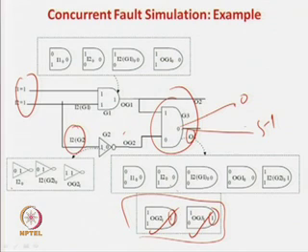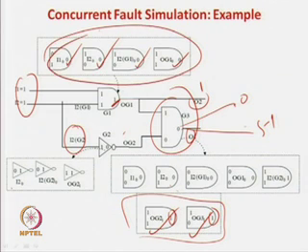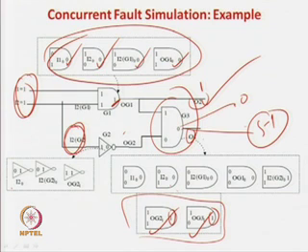But similarly, you can see that at O2 also some faults can be detected. Now, what are the faults that can be detected? Here the answer is a 1. So, in the normal case O2 will be a 1, but here this is 0, this is 0, the output is 0, the output is 0. So, all these 4 faults are detected at this net, and this one, sorry, O2 G1, that this fault and output stuck at 1 fault are detected at this net.